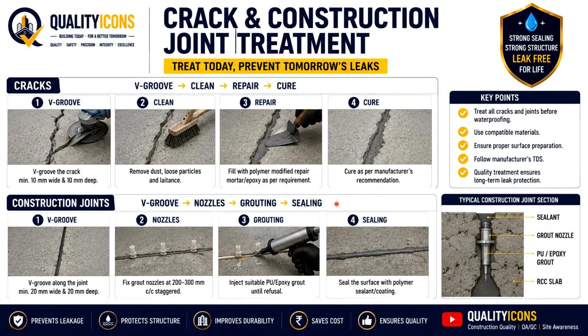For construction joints, the sequence is V-groove, install injection nozzles, grout and seal. This is the construction joints. The packers fixing, inject suitable PU or epoxy grout or cementitious grout until refusal. Seal the surface with the polymer sealant or coating. Typical construction joint section: sealant, groove, nozzle, PU epoxy grout, RCC slab.